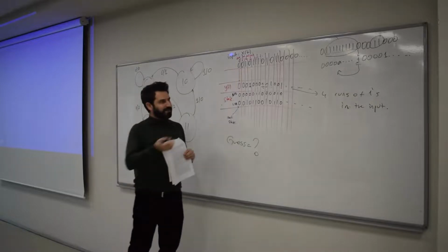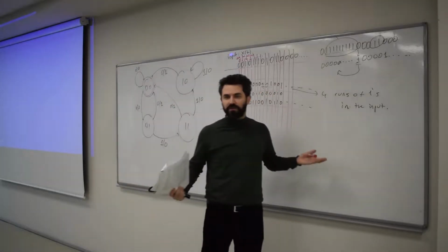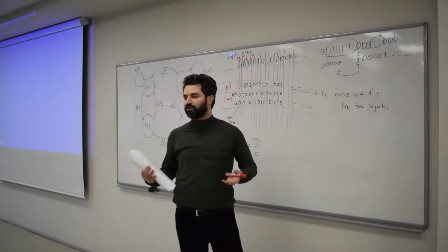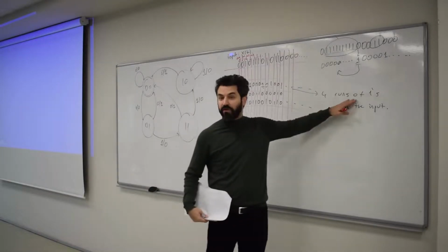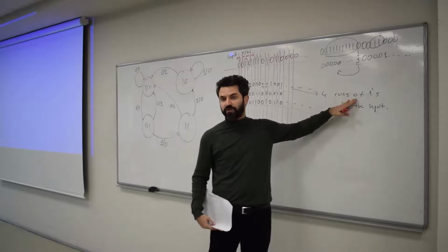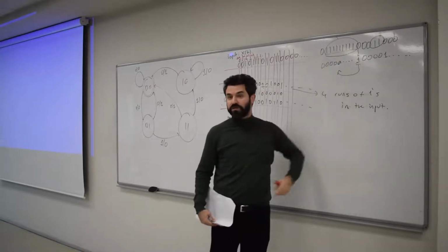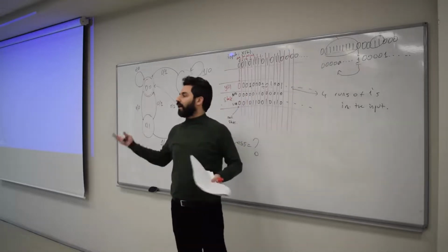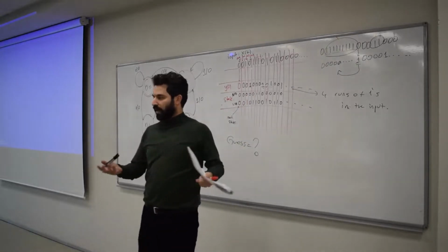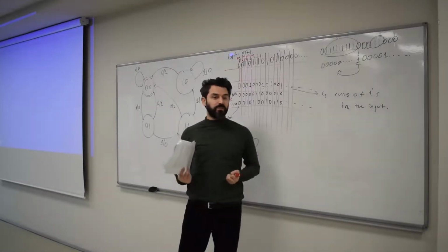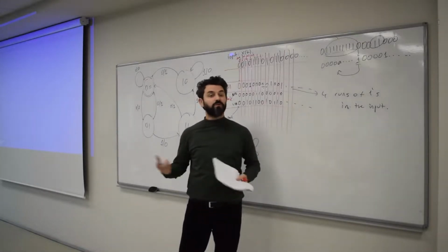You may see that, well, this is a very simple logic. I mean, runs of 1s. I mean, who would need runs of 1s in a digital circuit? Well, it's very, very critical, important information for digital circuits. Okay, runs of 1s are very, very important because if you got those runs of 1s, for example, bigger than 100 or 1,000, okay, that would be a big problem for communication systems, because communication systems use these bits to synchronize.